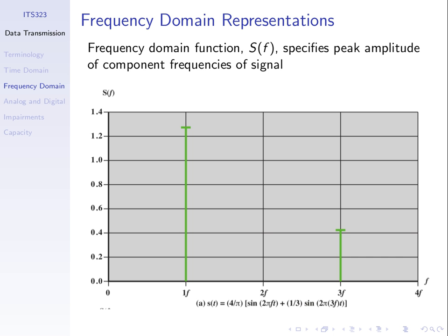Each sinusoid has some frequency. If we have the structure of the signal where the components have frequencies which are integer multiples of one of them, 100, 3 times 100, then the resulting signal has some common structure where the fundamental frequency is the base frequency of that component.